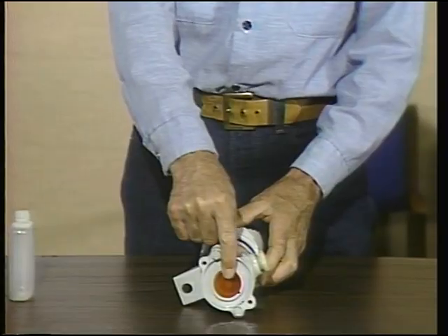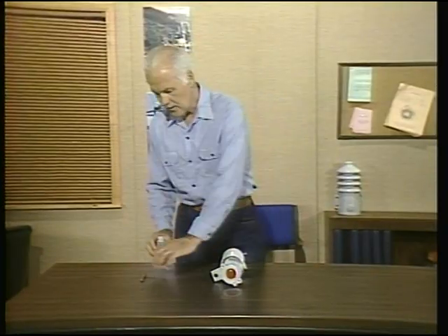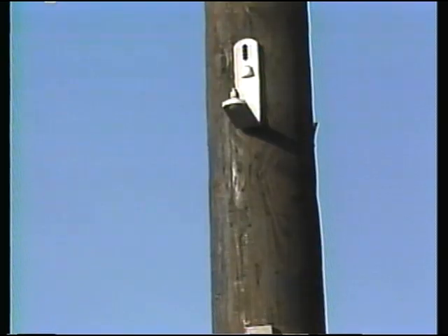and the cable entrance. This terminator is part of a kit which also contains a plastic bottle and a connector. The plastic bottle is used to collect the insulating fluid that's displaced from the terminator when the cable is installed. Okay, let's see how this terminator can be installed. In our example, the terminator will be supported on a pole by a galvanized steel mounting bracket.